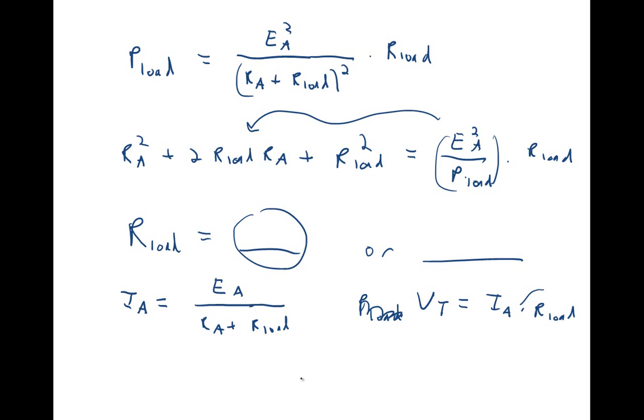and now we need the torque. Well, the torque is going to be equal to K phi, because there's no rotational losses, so we can just say developed torque is the same as the output torque. K phi times IA. Now we know K phi, we found IA, we can get the developed torque. And so that gives us everything we need for that. Okay. So that is problem 6.